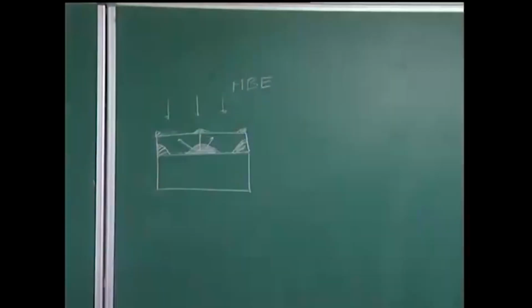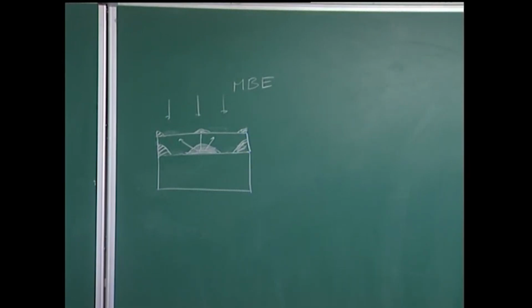There is clearly an absence of any epitaxial stresses, because the whole origin of stresses in the epitaxial case is the need for the system to match atoms or atomic planes of the lower layer with the substrate. Why does the system want to do this? The system wants to do this because if there is an epitaxial interface or a coherent interface, the interfacial energy cost for the system is small.